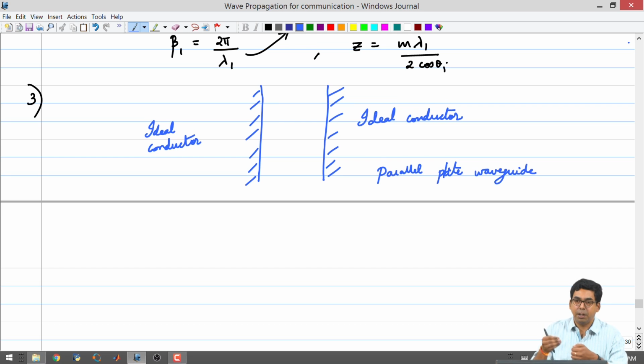The consequence is that you are going to have propagation that is slower than in a homogeneous dielectric medium, because it does not follow the path of least distance between point A and point B. It is bouncing multiple times and reaching the other side. So, you can call these kinds of configurations delays. You are taking a signal and passing it through this configuration at a specific angle. It will be delayed by so much time when it reaches the other side. So, in a simple scenario, a waveguide can be used as a delay element.